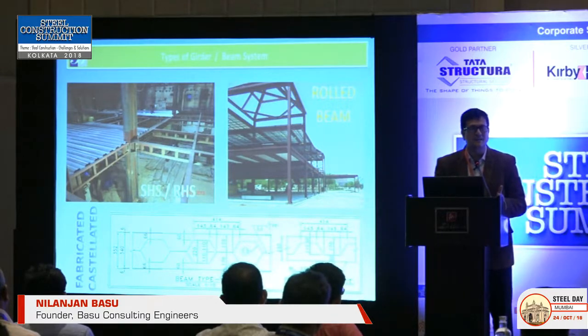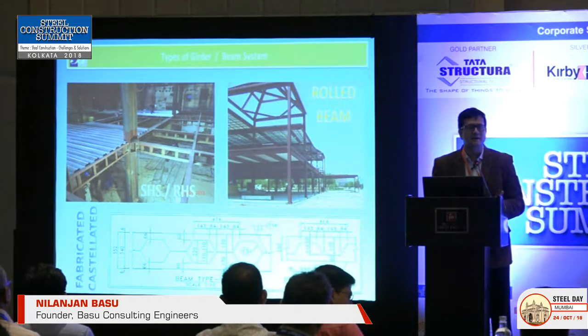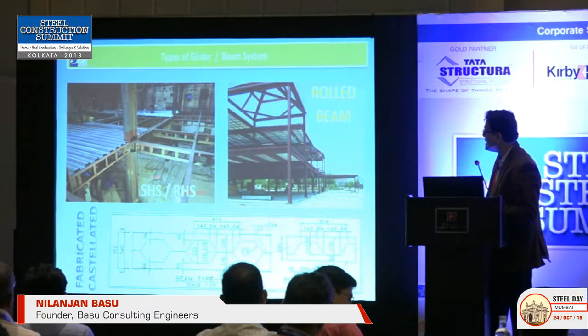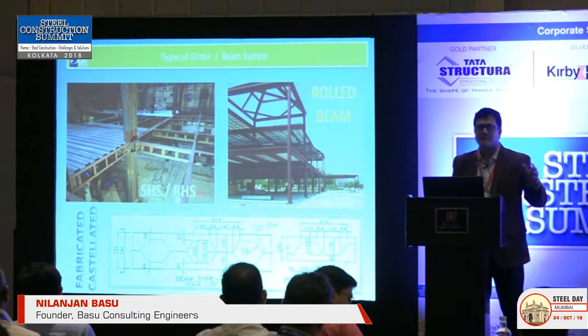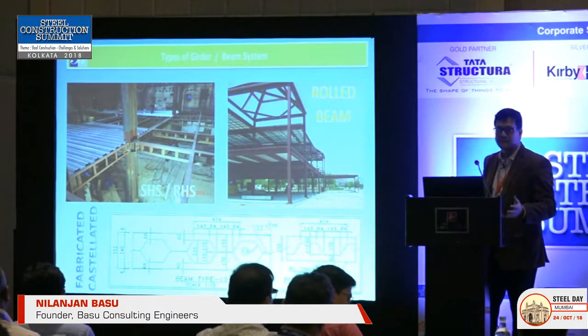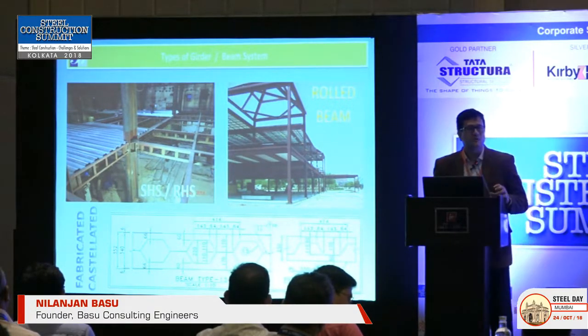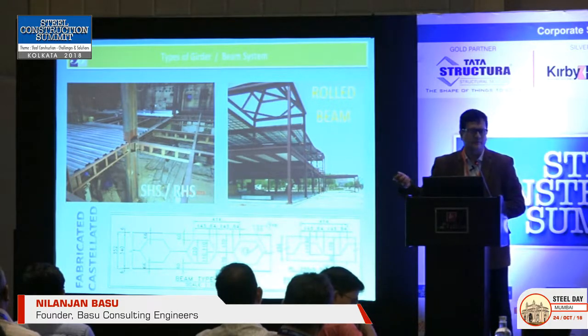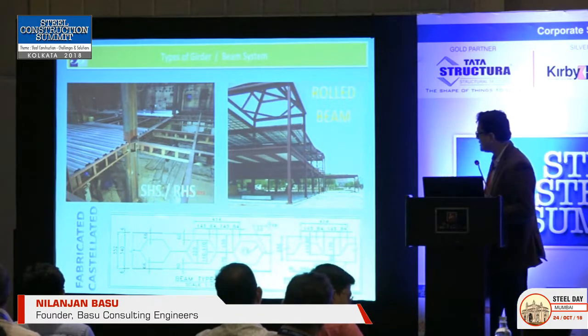Because of the biaxial strength of a hollow section, it's really an underutilized section in India. People need to realize the benefits of hollow sections. It can actually transfer any structural load of any building. And it has the benefit that the depth can also be restricted. For a 14-meter span, we have not gone beyond 500 millimeter depth. That's for one of the projects which we did in Calcutta, Globe Cinema.